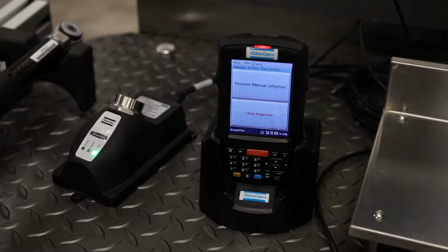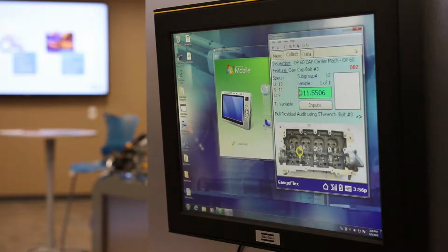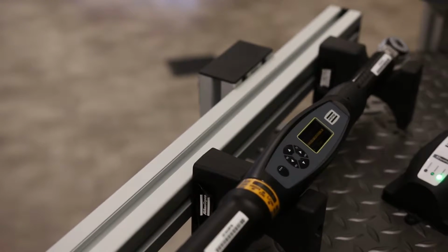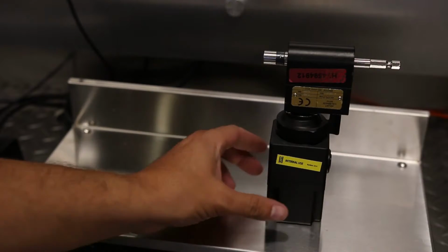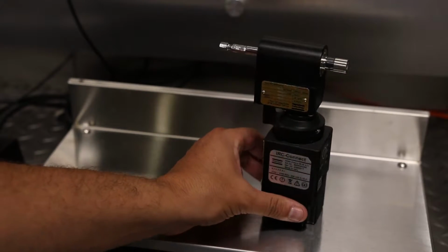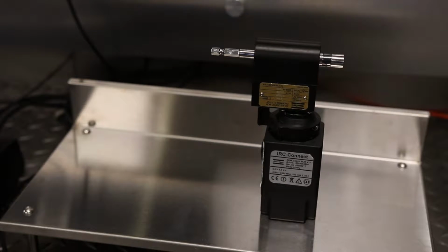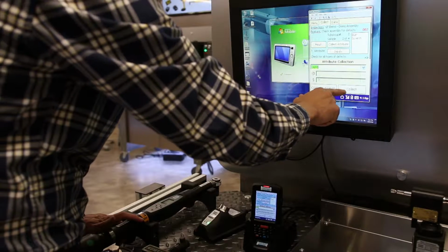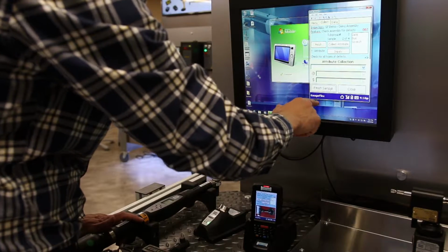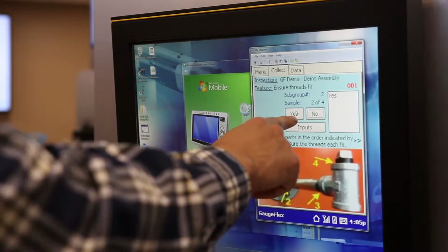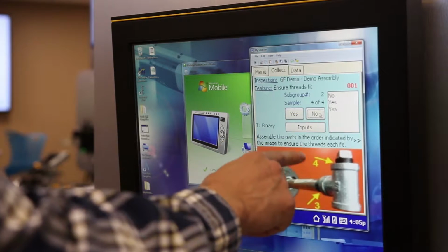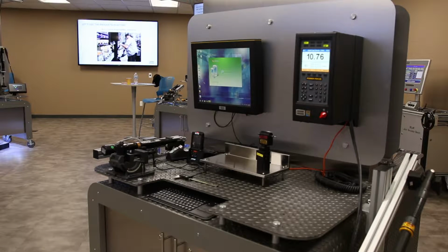It offers three main quality plateaus. 1. Variable data collection, including torque data, which can be with the ST wrench for residuals or dynamically with the IRTTB or SRTTB along with the IRC Connect. 2. Collecting attributes, which includes visual inspections for defect analysis. And 3. Binary data collection. Utilizing the GaugeFlex will help to reduce or eliminate scrap, rework, rejects, maintenance, service, warranty claims, and consumer liability.